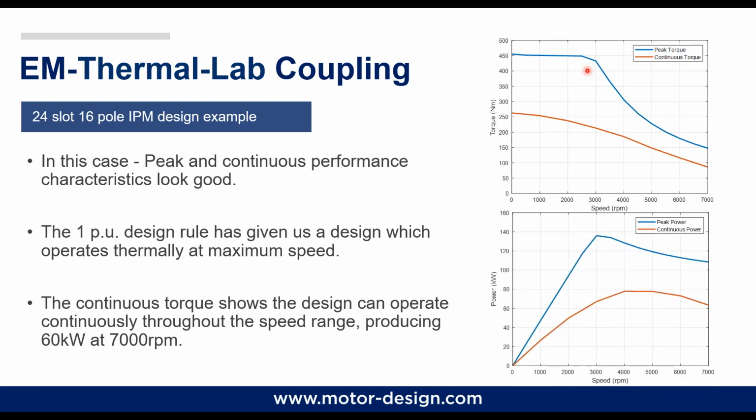What we do there is starting from a current, we calculate the losses at that temperature, and with those losses, we calculate again the temperature inside the machine. The new temperature is updated back in our electromagnetic model, and automatically we recalculate the losses, which are going to change with a different temperature. So we do a few iterations before getting to the point.